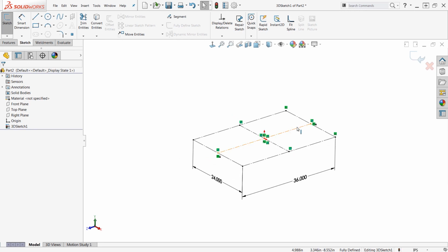All right. I'm going to keep my green boxes on for a while. Typically, I don't like to have those on because I know exactly when I'm working in SOLIDWORKS what relationships I'm adding at any given time. Now, just to review sketches, in order to fully define a sketch, you have to have two things: relationships and dimensions. I list those in that order because relationships I do first. I capture all the relationships based on my design intent, and then I'm left over, typically, with the key dimensions that I might want to change later on.